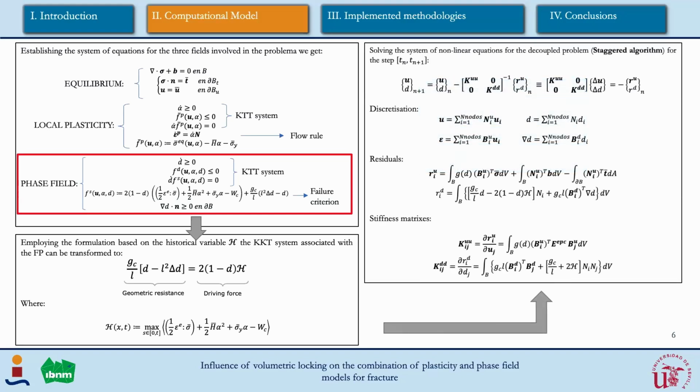With that, using the principle of virtual work, we can get the system that can be implemented in our finite element program, and we get the residuals and the stiffness matrices for the displacement field and for the phase field. For the first methodology, the V-bar method, we are going to work on the residual and the stiffness matrix for the displacement part.